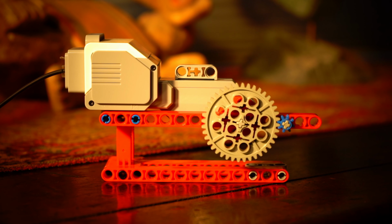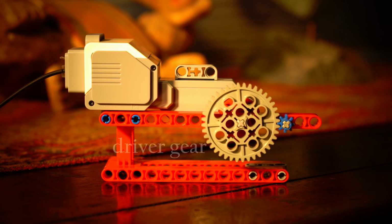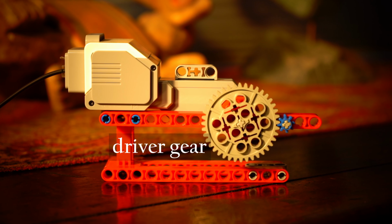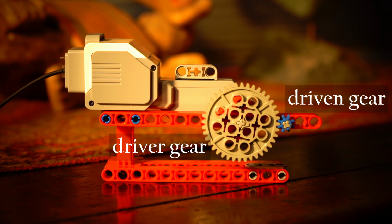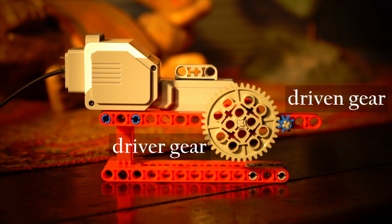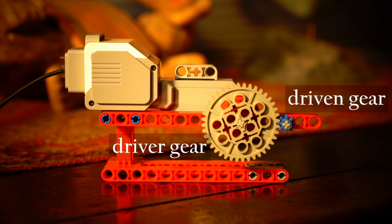But first, some basic gear nomenclature is required to distinguish driver, driven, and idle gears. The driver gear transfers power and is closest to the motor or power source. The driven gear, sometimes called the follower, receives power from the driver gear. Here, the large gray driver gear provides power to the smaller blue driven gear. Note that the gears rotate in opposite directions.